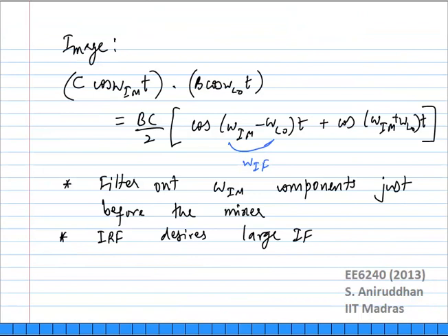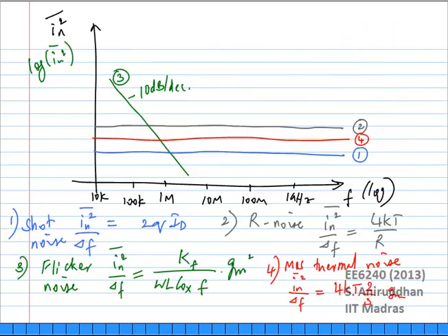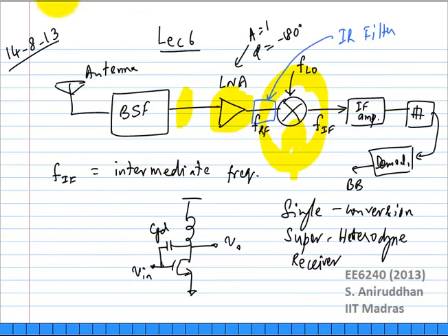So apart from that, suppose you choose a very high IF. Maybe you don't need an RF ADC, but if let us say IF was a couple of 100 megahertz, you can actually digitize the signal right here. You don't need an IF amplifier. You just go ahead and digitize the signal right here, immediately after the mixer, where your signal has been transferred to IF.